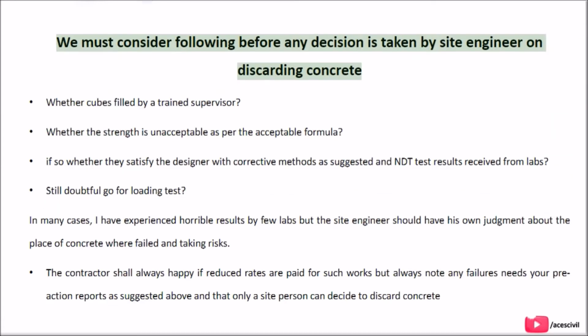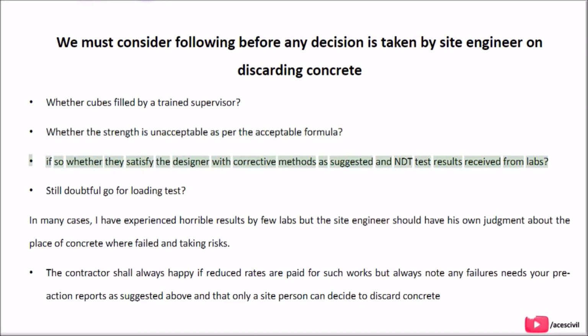We must consider the following before any decision is taken by the site engineer on discarding concrete. Whether the cubes were filled by a trained supervisor. Whether the strength is unacceptable as per the acceptance formula. If so, whether they satisfy the designer with corrective methods as suggested and NDT test results received from labs. If still doubtful, go for a loading test.